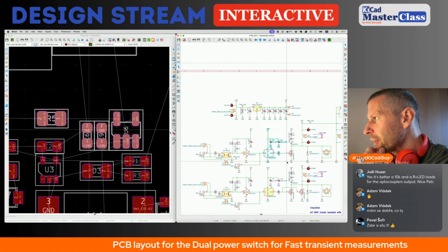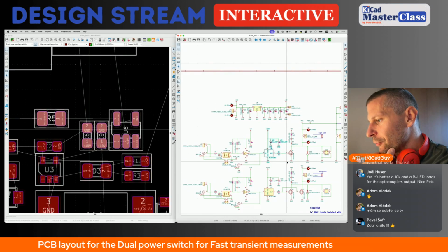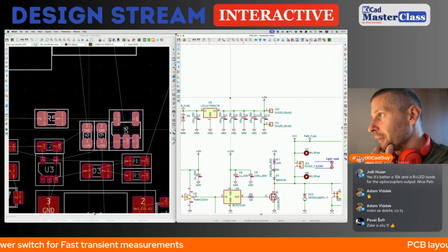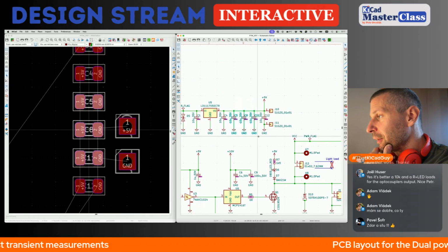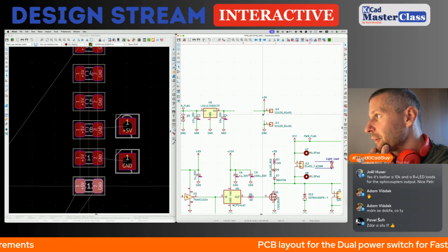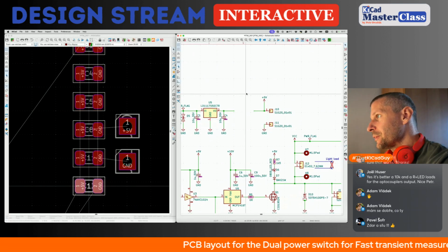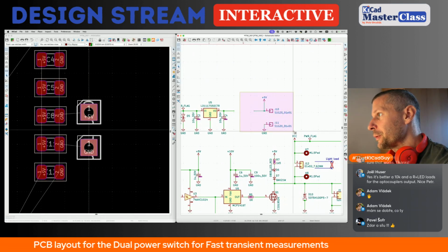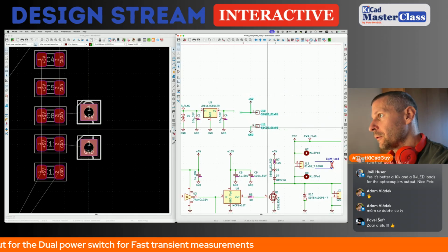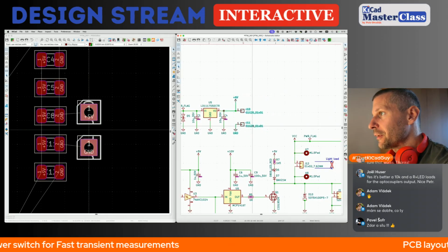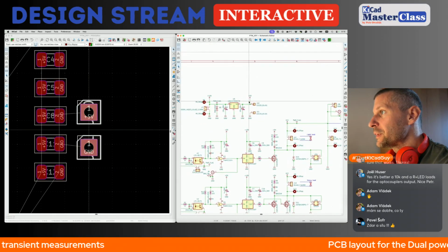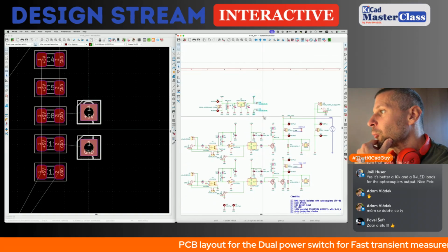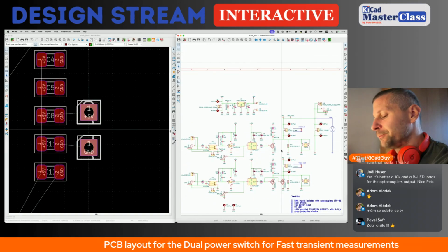The gate driving circuit is supplied from 10 volts. So it means I can significantly reduce the capacitor battery here, which saves a lot of space on the PCB, and it also makes the entire circuit simpler. This way, yes. The 5 volt is only for logic.